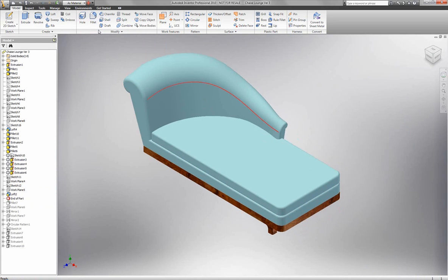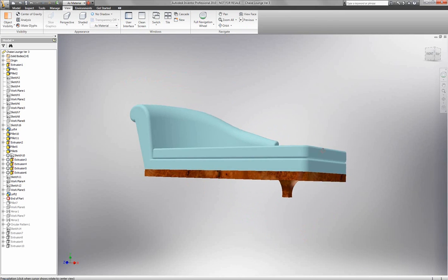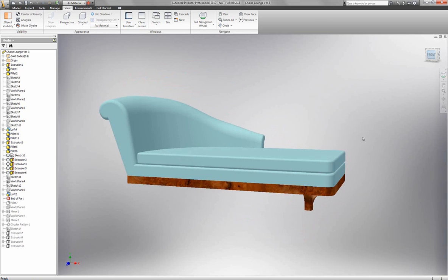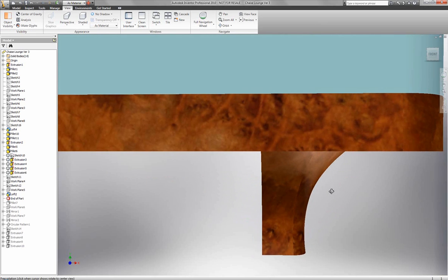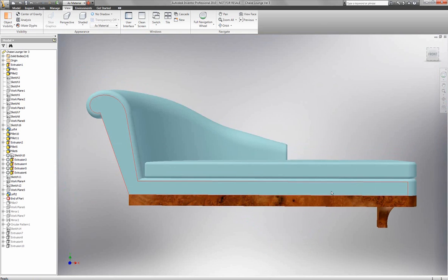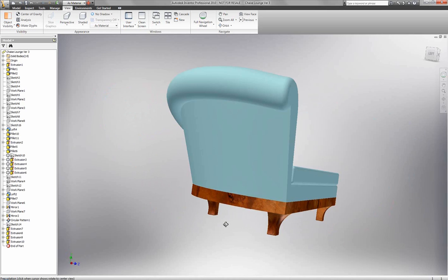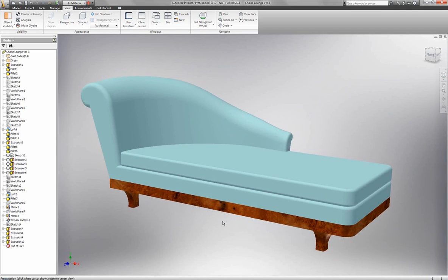I can also, inside of Autodesk Inventor, build off the actual manufactured or cut wood components for the bottom of this chair. So I can create a bill of materials of all the different components, legs, in this case I only have one right now, and all the different cut components, so I can make sure that I can actually build what I'm creating digitally. Go ahead and roll forward in the design process a little bit here, and we can see the remainder of the chair legs that I've created within Autodesk Inventor. So now I get a nice realistic approach of, can I build this model? Is this a realistic design? And how am I going to manufacture this?